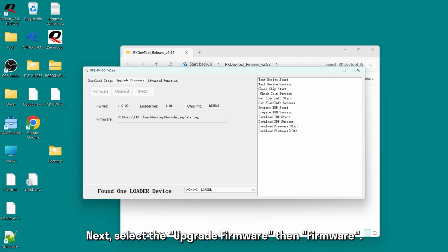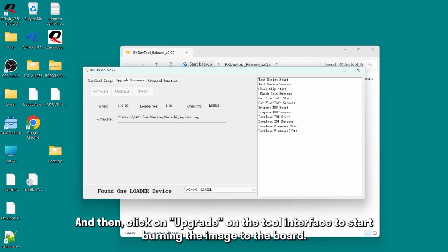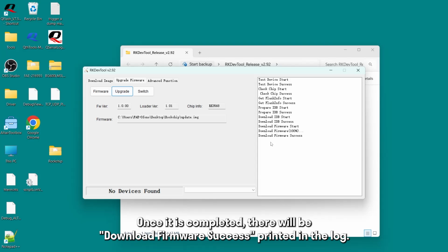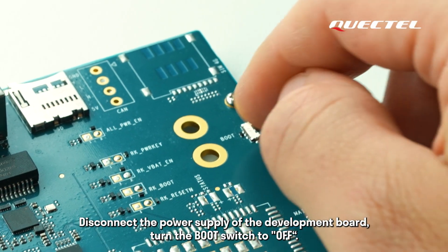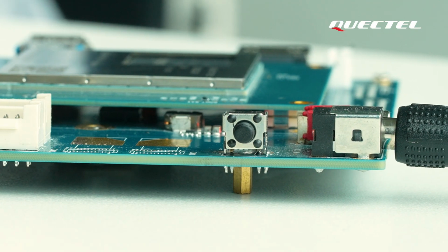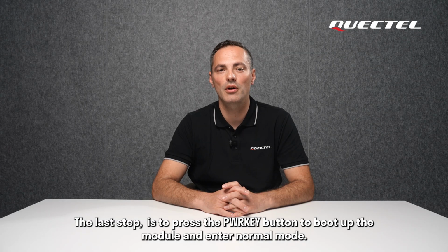Next, select Upgrade Firmware, then Firmware. Double-click to select and load the update.img file as compiled in previous steps, and then click on Upgrade on the tool interface to start burning the image to the board. Once it is completed, there will be Download Firmware Success printed in the log. Disconnect the power supply of the development board. Turn the boot switch to off, and then power up the board once again. The last step is to press the power key button to boot up the module and enter normal mode.